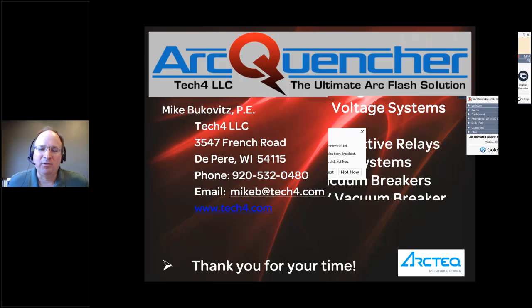So that's best done probably during an annual maintenance outage when you have downtime. The easiest pieces of equipment to install in are either a low voltage switchboard or, on the medium voltage end, metal-enclosed switchgear. Those are simple. It's a little bit more complex when you get to low voltage draw-out switchgear or metal-clad gear. That's kind of in the middle. And motor control centers are the most time-consuming asset on which to install arc flash sensors. Most variable frequency drives are easy in comparison, depending on the drive configuration. But MCCs are, from a labor point of view, definitely the most time-consuming. Great question. Thank you for that.